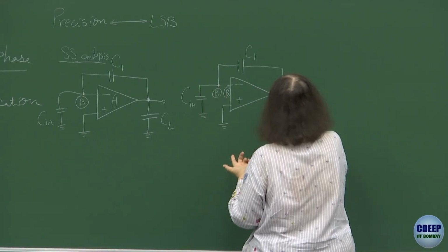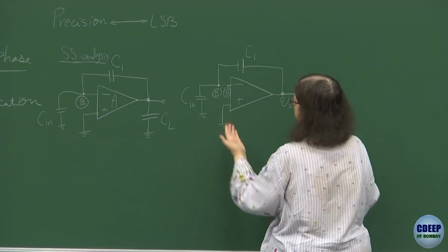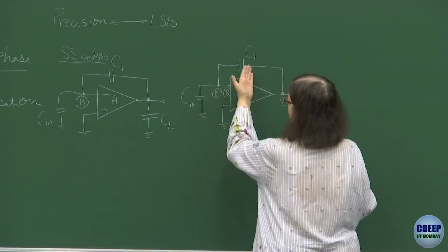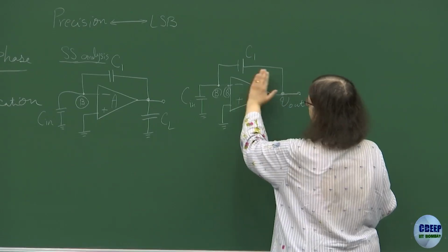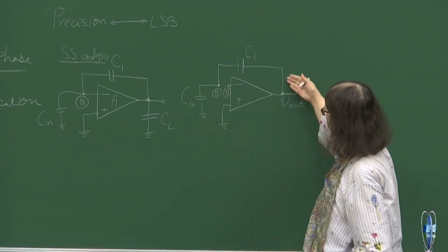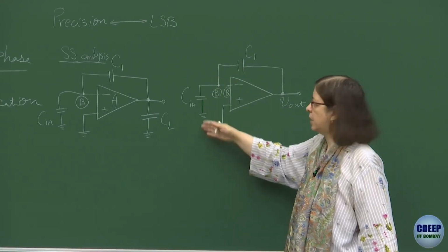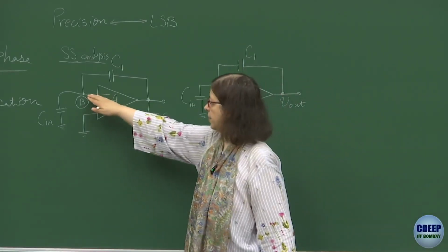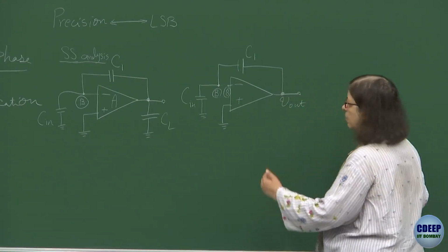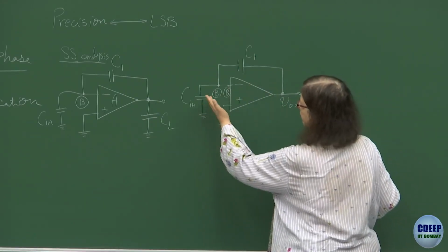This voltage is actually a fraction of the output voltage, and it's simply capacitive division, because if you look from the output, the output will see C1 in series with C, since this branch doesn't draw any current. Also, we see a kind of linear feedback.